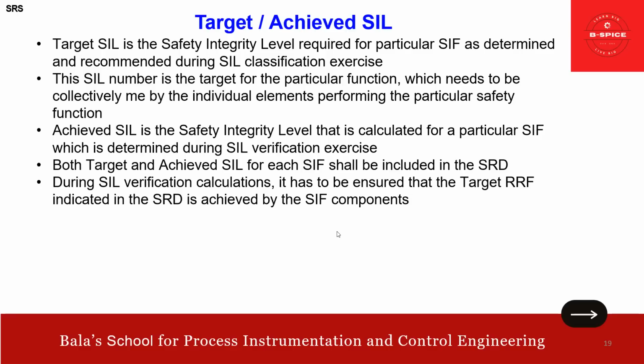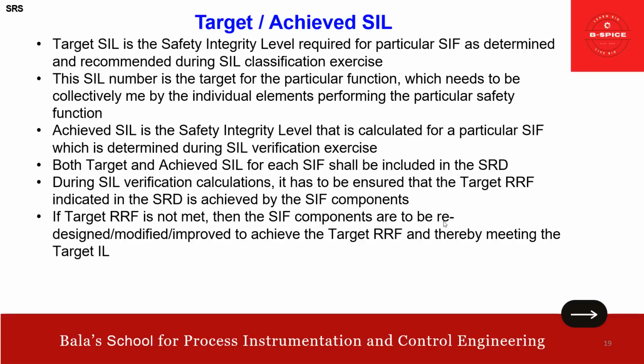During SIL verification, it has to be ensured that the target RRF, the risk reduction factor, friends, indicated in the SRD is achieved by the SIF components. Like I highlighted, for SIL 2, during verification we have to see whether the target RRF is achieved by the SIF components. If the target RRF is not met, then the SIF components are to be redesigned, modified or improved to achieve the target RRF, thereby meeting the target SIL.